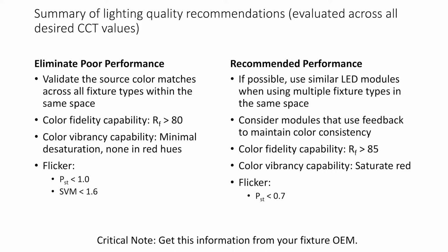What about flicker? There's a measure, PST, where if the value is 1, 50% of the population can see the light flickering. So you want this fixture, whatever driver they put in, to have a PST of less than 1. And then there's something called the stroboscopic visibility measure. Again, 1 is just visible. So if you ended up with a fixture that was greater than 1, somewhere on the order of 1.6, it's probably poor performance. You've never asked for these before, I doubt.